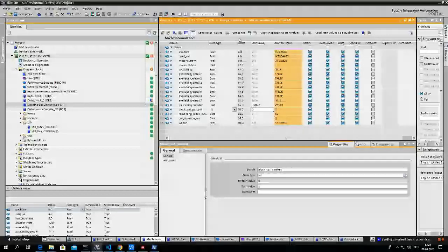This is due to a topic Siemens introduced: optimized blocks, because they have an access optimization built in. In these blocks the data is not in a plain order, but in a specific kind of order where we can't access offsets. Sometimes, when we check the legal issues and integrate the rest, then we can also read out these optimized blocks. But currently we have to adjust the blocks to non-optimized access.